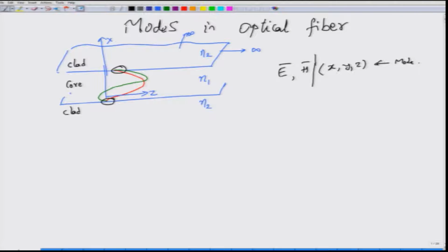Okay. This need not be just an optical fiber. In fact, this waveguide is actually an integrated optical waveguide circuit. So, in an integrated optical device such as a laser, a photodetector or waveguide modulators, you would see all these types of waveguides. If you look at the field behavior in the core, they would mostly resemble the red and the green curves which stand for a half sine wave or a full sine wave, half sine wave being the fundamental mode, full sine wave being the next higher order mode.